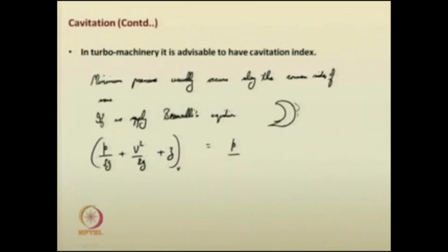At the downstream, there will not be any velocity head, because in the liquid form we are not assuming it to exist there, and there are some losses downstream. So, this Bernoulli's equation can be used for identifying the cavitation index. With that, we have given a brief view on the turbo machine aspects.